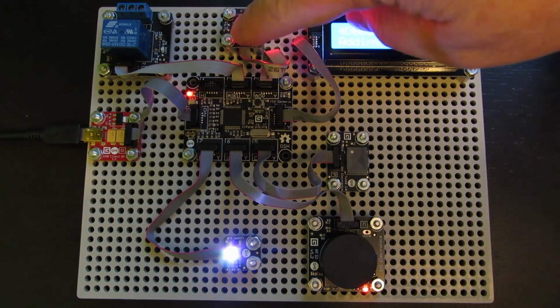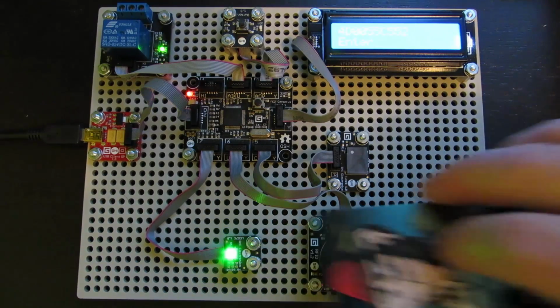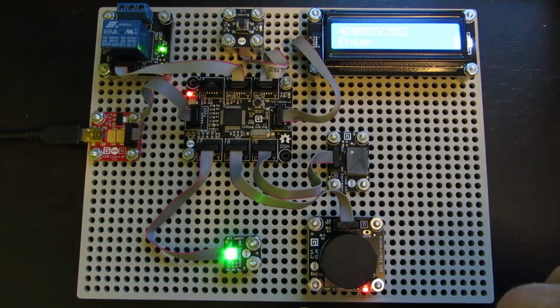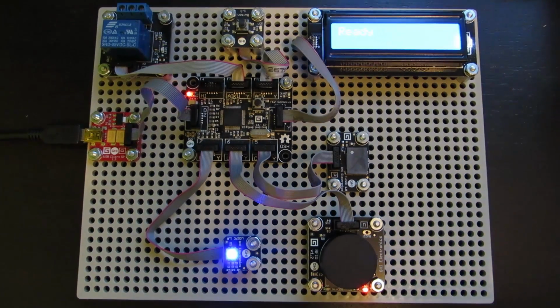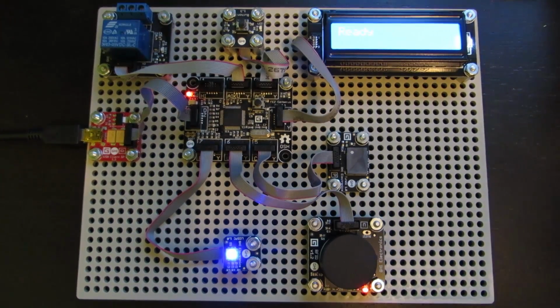So let's turn off learning mode. It's gone back, our LED's blue, it says that it's ready. We'll take the one that we didn't add and give that a scan. Yeah, it's denied. Then we'll take the card that we did add, put it on there, and it says it's entered. Our LED goes to green, our relay turned on, and then it turned off after the 3 seconds, and we heard that little beep.